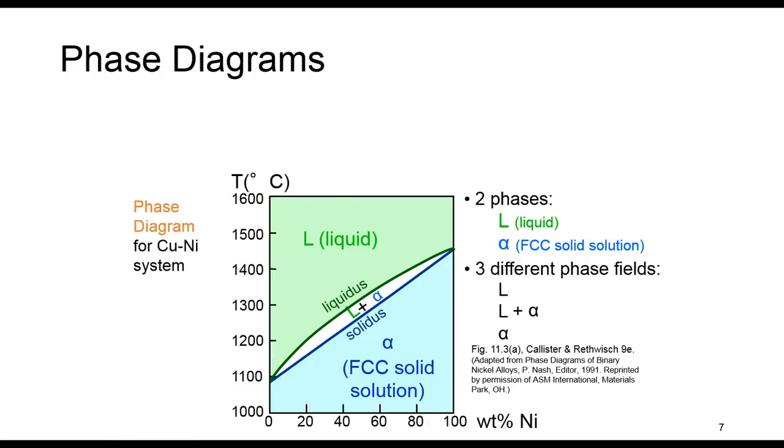The chart, like this chart that talks about the Cu-Ni system, copper nickel system, shows what different phases occur and exist at different conditions such as temperature and pressure, in terms of the weight percent composition of one of the elements. This chart is called a phase diagram. It indicates phases as a function of temperature, composition, and pressure, in simple words. For this course, as we have two components, Cu and Ni, we call it a binary system, and the independent variables are temperature and composition on the horizontal axis.